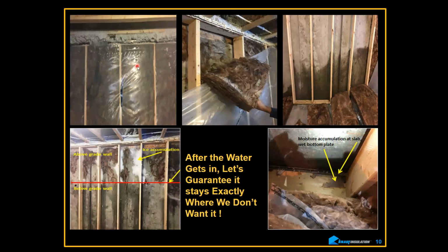But you can see the results that happened here. These were sticking to this concrete because the moisture got frozen. You can see it here on the bottom. Here's the grade line. I didn't even have to go outside and measure because you can see where grade is here. As it melts, water drips down. You create problems on the bottom of the sill and through here. You can see the draping on the upper right-hand side here. This was really, really wet stuff.